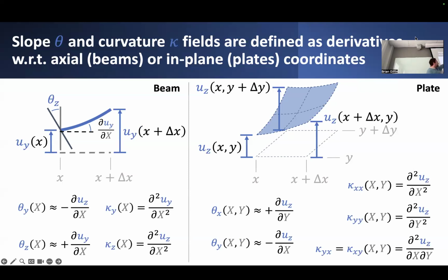If you were to look at what happens to the orientation of this beam, and more specifically, the orientation of its neutral axis, the neutral axis might incline a little bit, depending on how much this beam has displaced in a direction transverse to the axis. So the transverse displacements are really not axial displacements. Their direction is basically perpendicular to the axis of the beam.